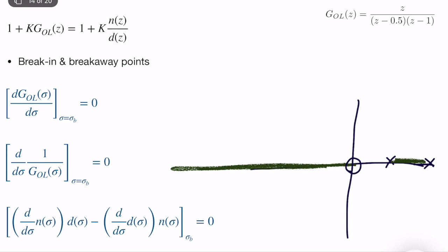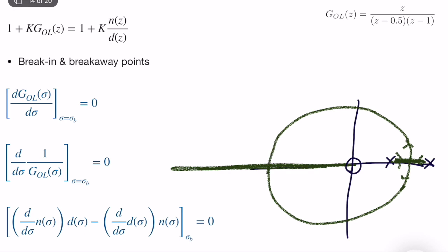That's great. So these two poles are approaching each other. They will need to break away, right? Because they should go to a 0 or an asymptote. So what I will do is they will just break away, like this. And this is in the Root-Locus. So some pole should go to 0 and some pole should go to minus infinity. What they will do is they will meet somewhere here. We don't know where. It can be inside the unit circle, it can be outside the unit circle.